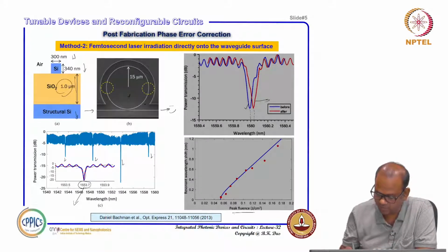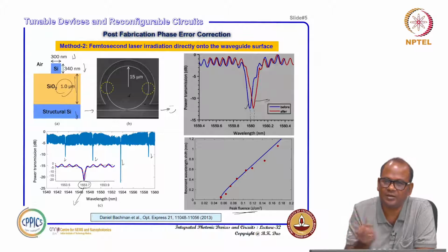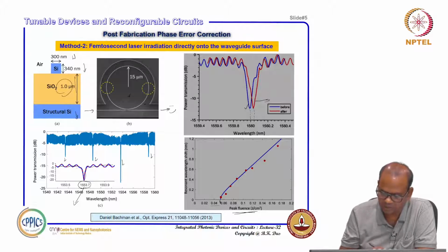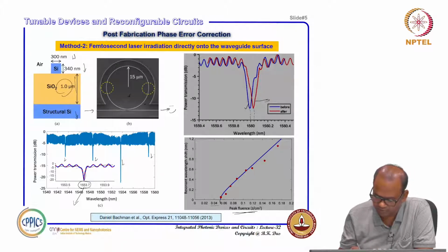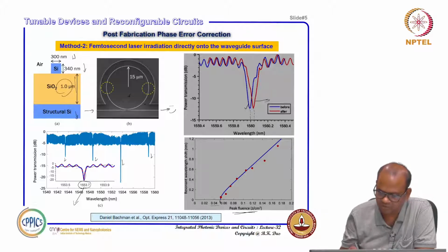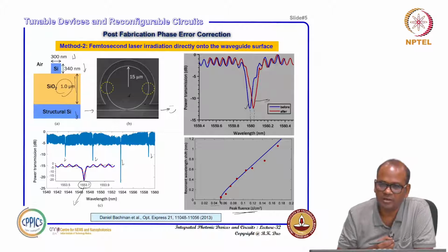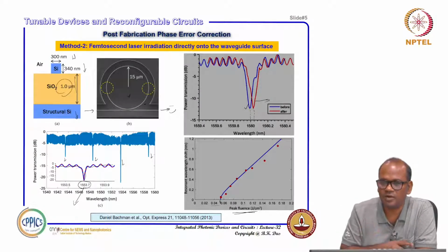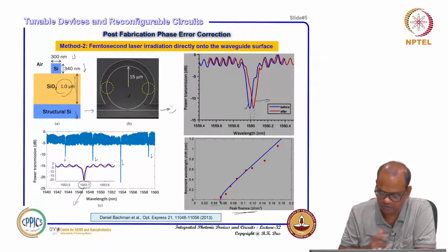Here it is shown peak fluence, joule per centimeter square, that is energy per unit area, which is kind of intensity you can say. If you increase it, up to here nothing happens. After this peak fluence, joule per centimeter square, that much joule is coming. Joule means how much power you are giving for a particular time slot, power multiplied by time, that is your joule, and you have to see how much area it is covering. So per centimeter square how much energy is being deposited, that is called fluence basically.